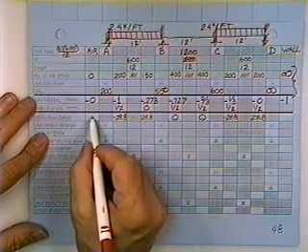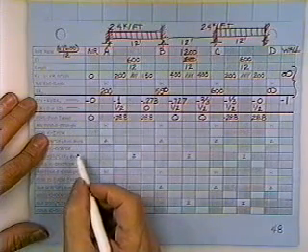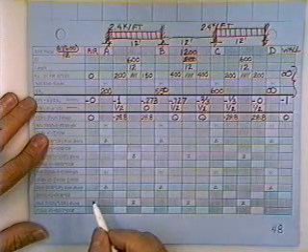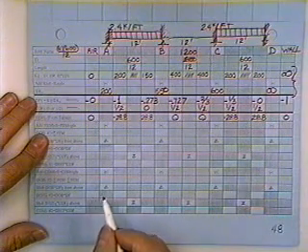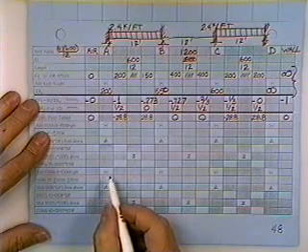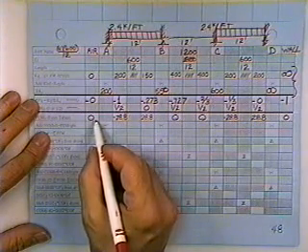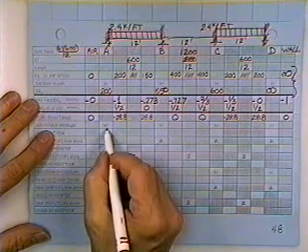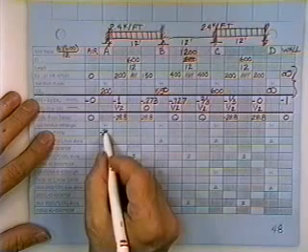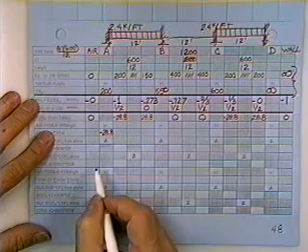Alright, incidentally, in the air, there was no fixed end moment. I forgot to mention that. It's just air. In the wall, there was no fixed end moment. It's just a wall. The only fixed end moments came from the beams. Now, I want to find out how badly I've torqued this guy standing at joint A. So I simply add the fixed end moment to the left and the fixed end moment to the right, and I get a minus 28.8. That's the sum of the two numbers to the left and right of that empty spot on the table.